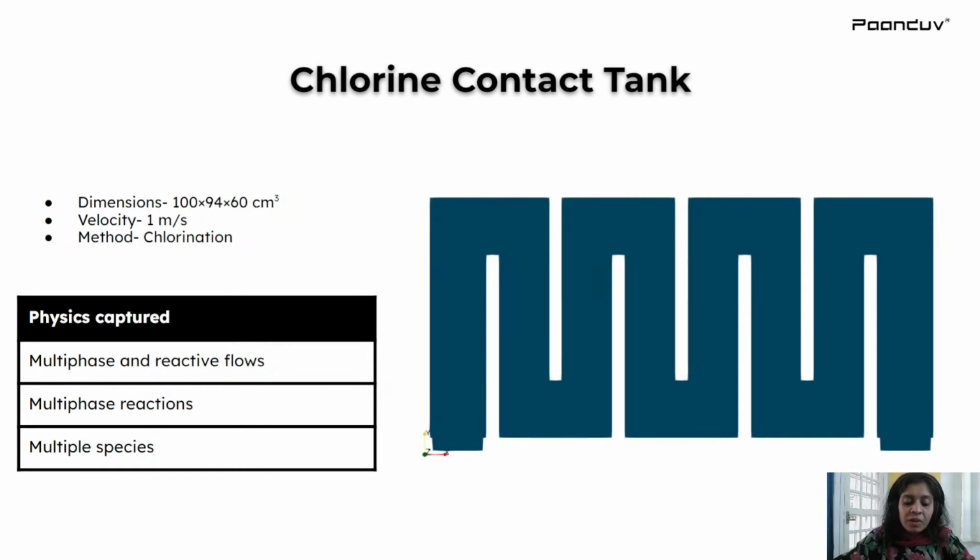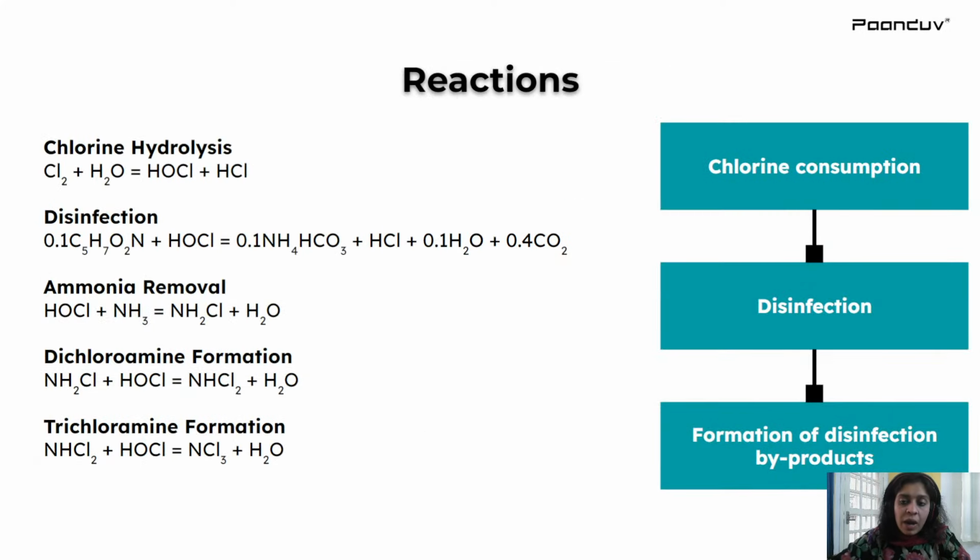You have impurities in nitrate form, in ammonia form, and in bromate form. All of those impurities react differently with water and with chlorine, and through the chlorination process, it will generate different byproducts, and those byproducts can be really harmful. So one has to identify which byproduct needs to be suppressed. So this is the heart of the overall wastewater treatment system.